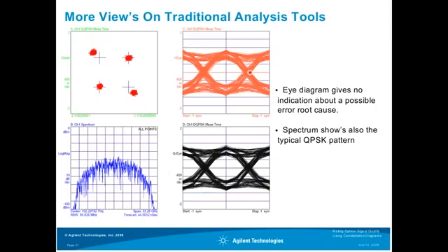I have shown here three examples of a transmitter we partly already discussed. The first transmitter is a very good transmitter, well aligned with an external cavity laser, and we can easily see here that we have a kind of white noise distributed error vector magnitude. This error vector magnitude is calculated to a value of close to 13%, which is a normalized value.